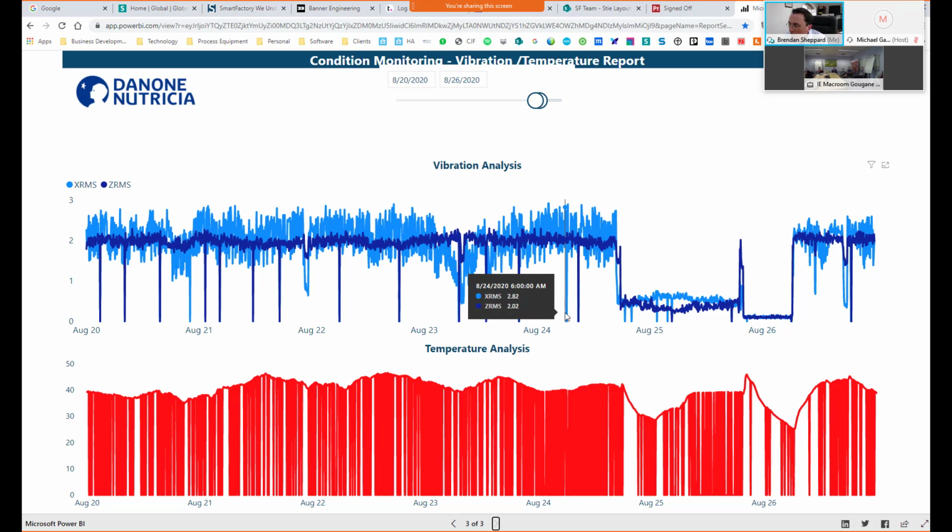Yeah, so that's a wireless sensor. It's in the M1 service duct. There's an air handling unit, and just to prove, because a lot of what we do for other companies is wireless sensors. I just wanted to demonstrate to Dan how easy it was. It's a little battery powered unit that takes a short period of time to install. And here we're just looking at X and Z, but there's an awful lot more data available within the vibration analysis as well.